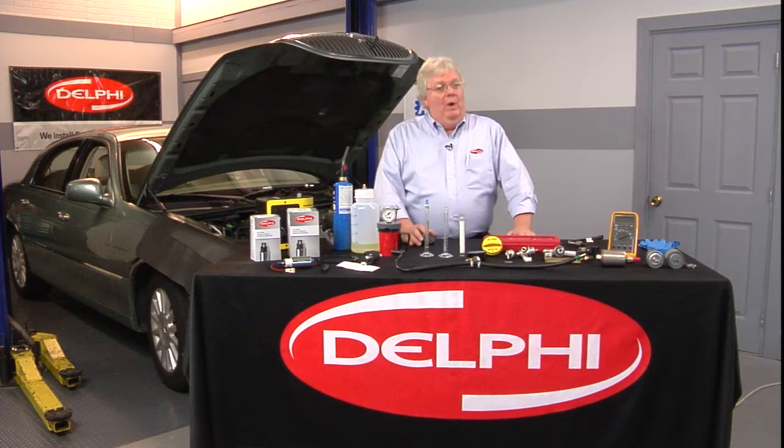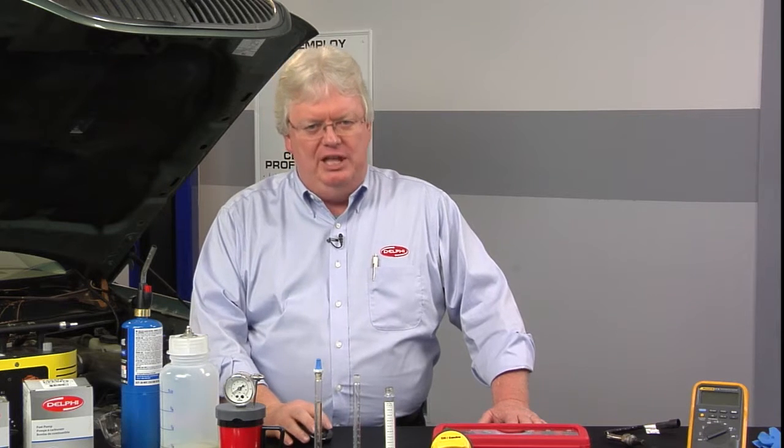That is great. When the fuel trim numbers go negative, as we saw on that chart just a second ago, that's because it's rich. We're taking some fuel away. We're reducing the amount of injector on time by a particular percentage, especially if both short-term and long-term go in the same direction. All right.